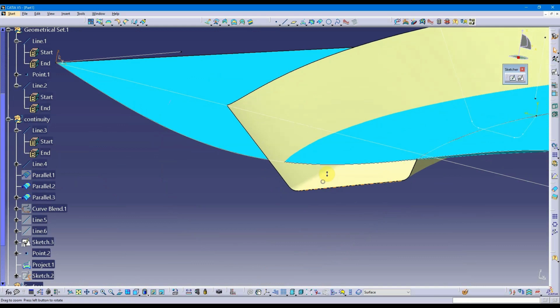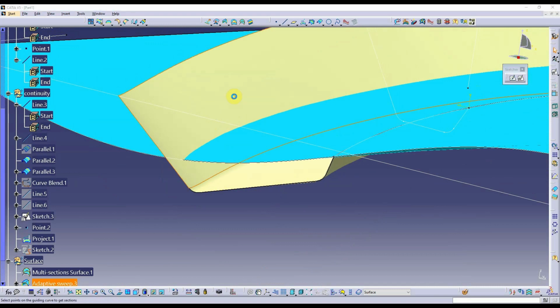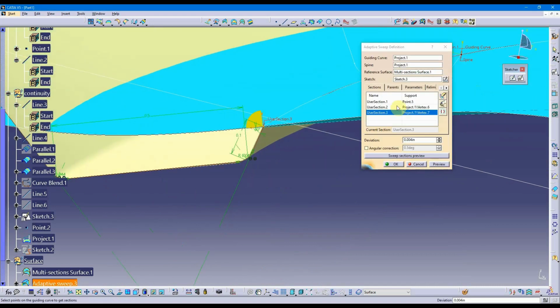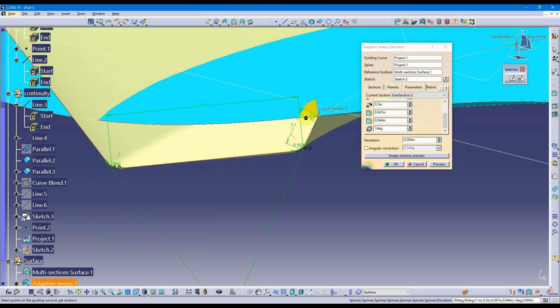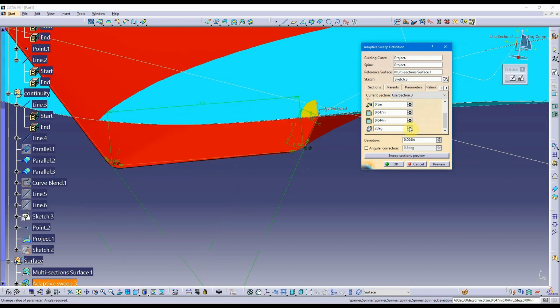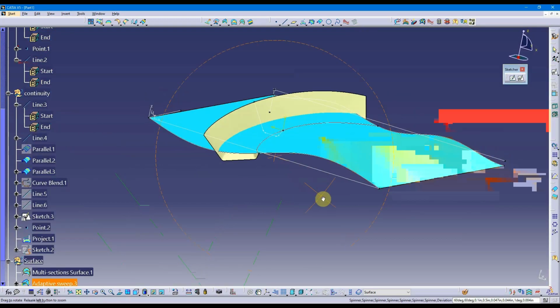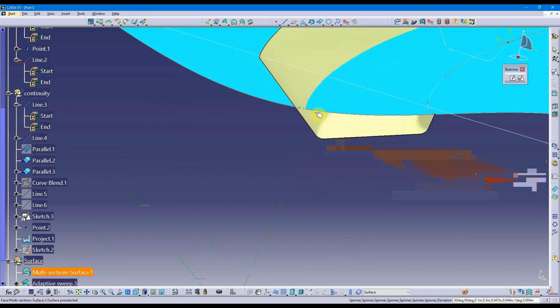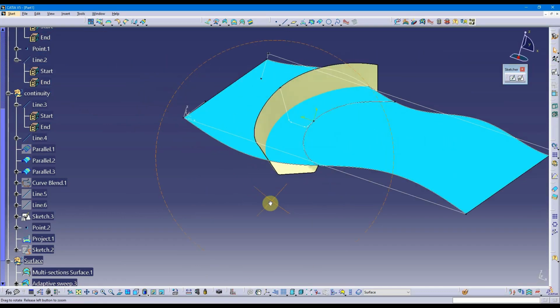See the angle here. That's really not too bad. One of the reasons why I put this angle parameter in, you can see it right there, there's a 1 degree angle parameter. That's the angle between the horizontal axis and its bottom, just in case I want to decrease. You can see it decreasing now just a little bit. So I can tweak that, adjust it slightly as my section sweeps around. Sometimes it will sweep around and you will lose some of your rounded corners, you'll get some issues, but I think that's looking really well.